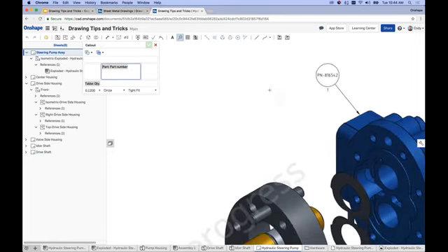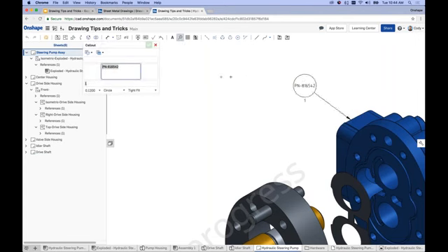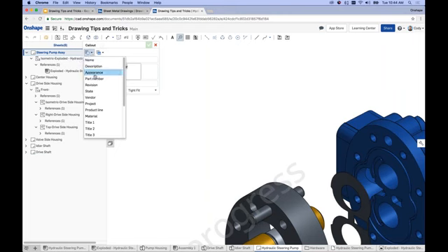So that's an important caveat that I would stress about balloons, or callouts more specifically, is they can be referenced to multiple things. A lot of users will just reference the item number, and that's fine. But if you have a need to reference something like, let's go in and look again, things like description or appearance, name, property, right? Or the revision. Maybe I want to show the revision as part of the balloon details. Material is another commonly asked one. So basically, just think of any type of property that you'd want to put into the callout.